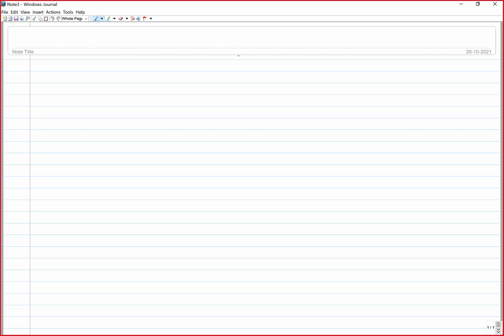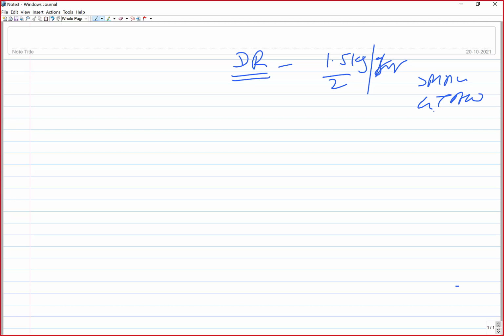Deposition rates are very interesting, no? It is the quantity of weld metal you deposit in one hour. It may range from 1.5 to 2 kg per hour for simpler welding, for processes like SMAW or GTAW, where we have to feed the electrode from outside.